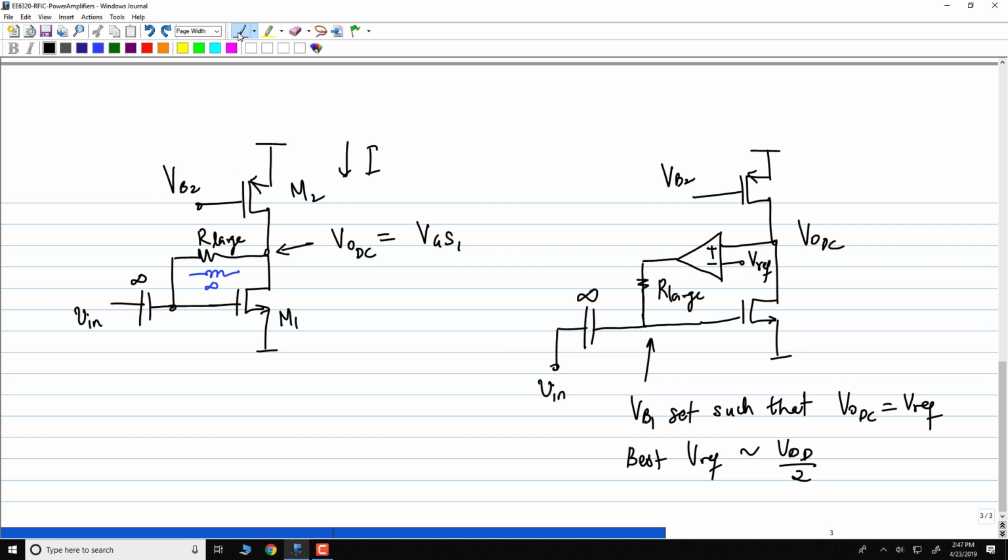What additional modification can you do to do even better than this? This is very good, but you can do better. Very simple. You can give the signal to the PMOS also. Remember, this was the active load that you studied first. You transition from the active load to the inverter. Do all of you remember this?